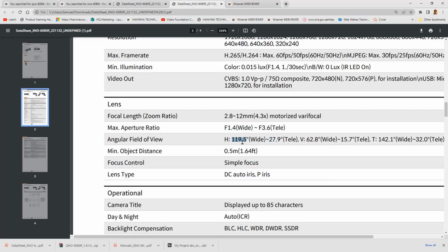So in most of the projects, lobby area, waiting area, corridor areas, you want to cover as wide as possible. But entrance area, number plate, car entrance, there you need to zoom in. So for those cameras, make sure you have higher zoom. But for the rest of the areas, you don't want 5 mm or 6 mm. You want as low as possible because lower means more wide you can cover. So that's about the first section of today.